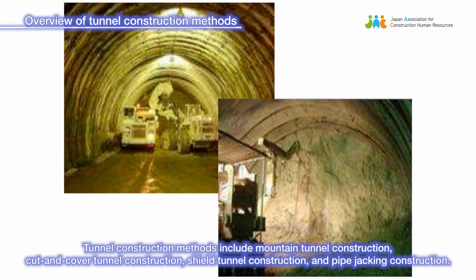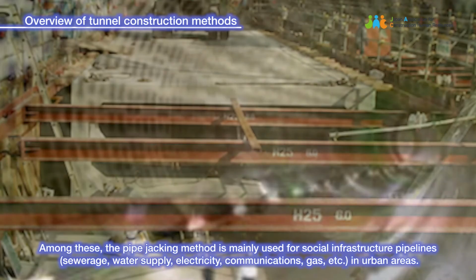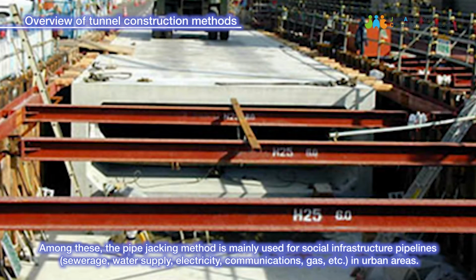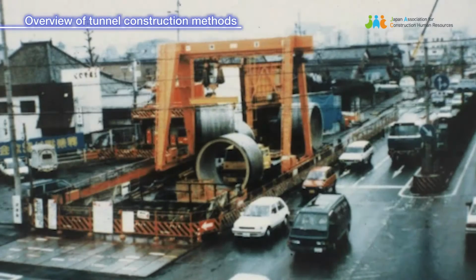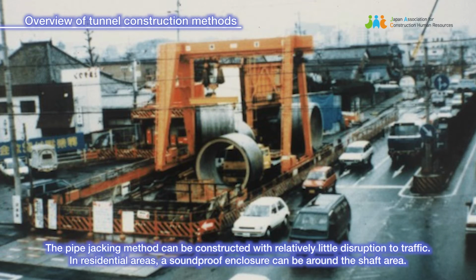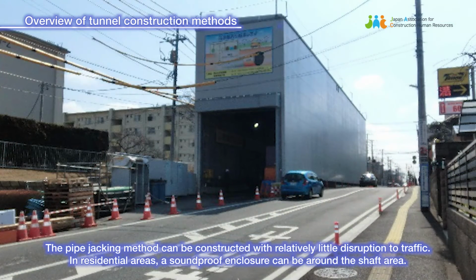Tunnel construction methods include mountain tunnel construction, cut and cover tunnel construction, shield tunnel construction, and pipe jacking construction. Among these, the pipe jacking method is mainly used for social infrastructure pipelines, sewerage, water supply, electricity, communications, gas, etc., in urban areas. The pipe jacking method can be constructed with relatively little disruption to traffic. In residential areas, a soundproof enclosure can be placed around the shaft area.